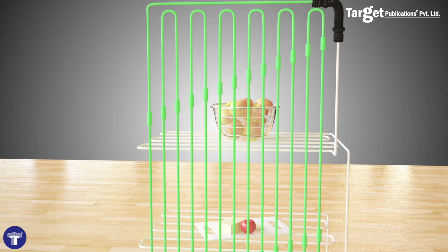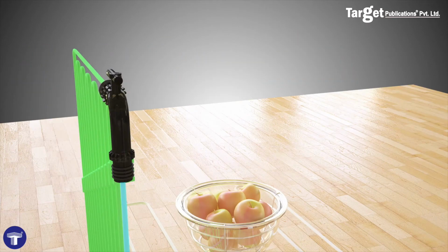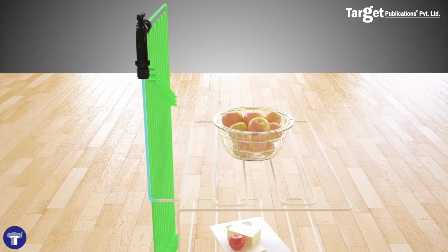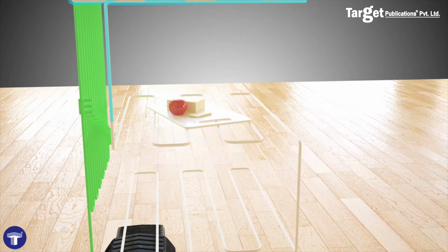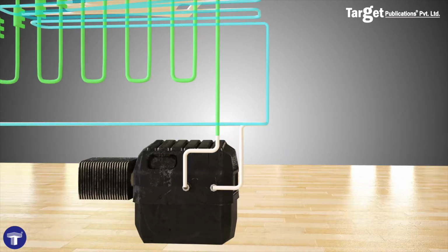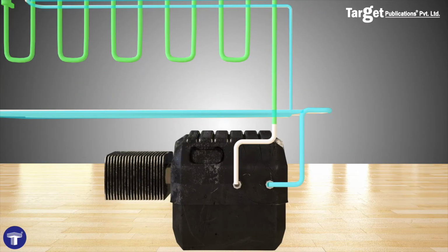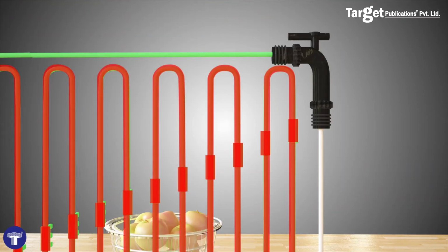First, there will be a sudden expansion of the gas from high to low pressure because of the expansion device. This cools this gas and converts it into a vapor-liquid mixture. After this, the coil fluid will absorb the heat from whatever region it has to cool. For example, it will take away the heat from the food that we are trying to preserve and convert it into vapor. Finally, the vapor is then heated due to external work in the compression device, and because of this external work, the vapor is heated rapidly.